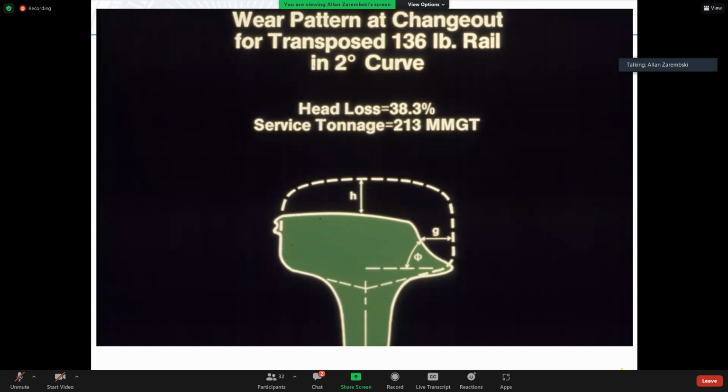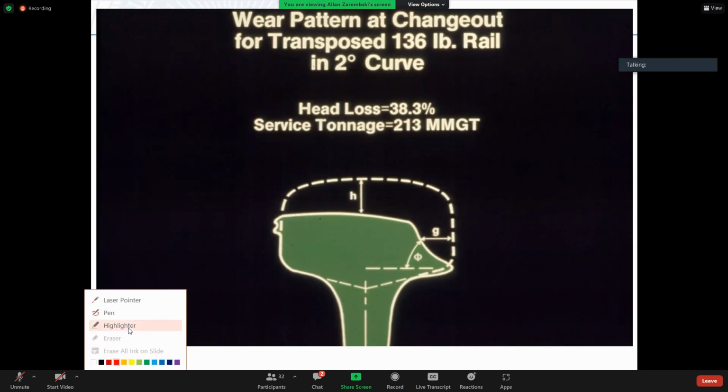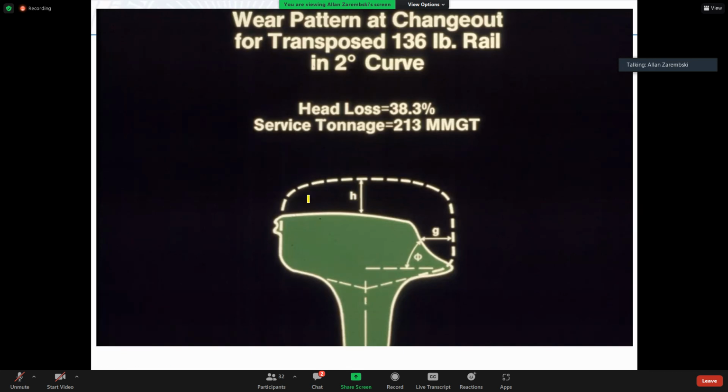So what you're seeing here is classical rail wear. Again, you saw that in the movie. You see this again here. Okay, so rail wear. This is the new rail section up here. This is a worn rail section such as you find in a curve. Why? Because we have side wear, which is most common with a curve. So we have side wear, which you usually see on the outside or high rail on the curve, because that's where the wheel flange rubs against the rail.